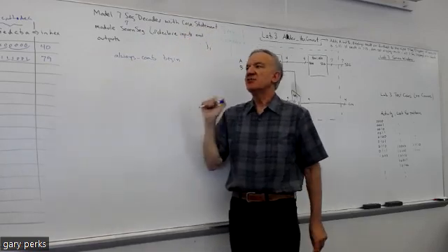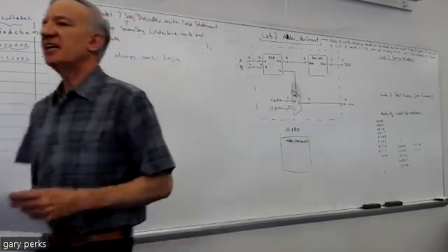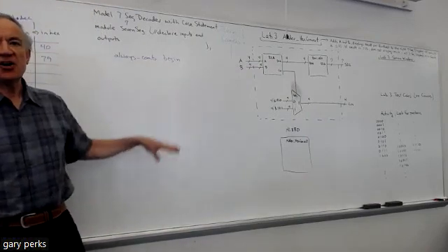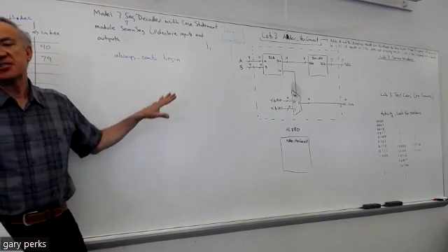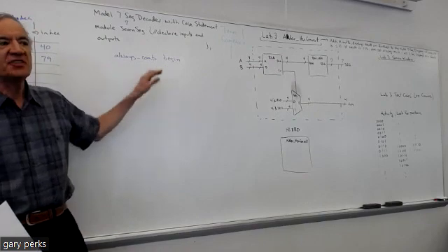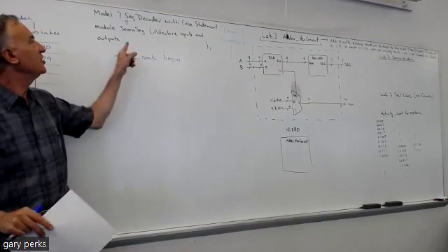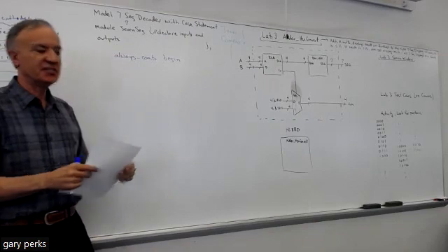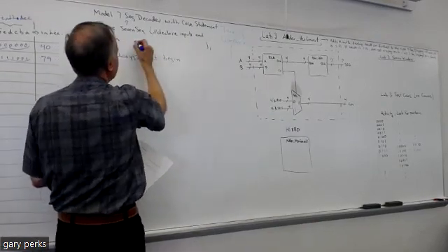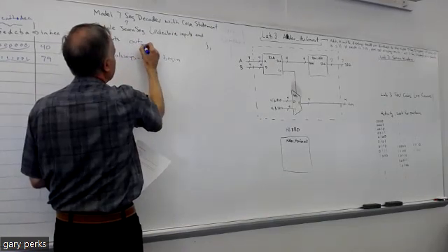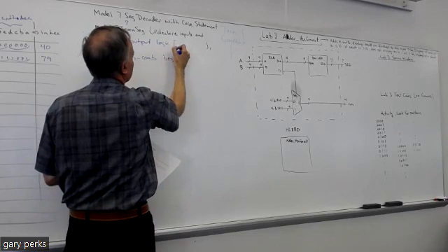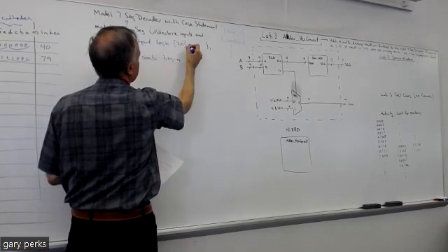Okay. Now, just like last time when we said any output that's within an always comb, there was an if statement; here it's going to be a case statement, but the same is true. Anytime you have an output within an always comb, you've got to put logic between output and the name of the output. So, when you declare your output for seg, it's got to be output and then logic and then 7 to 0, seg.